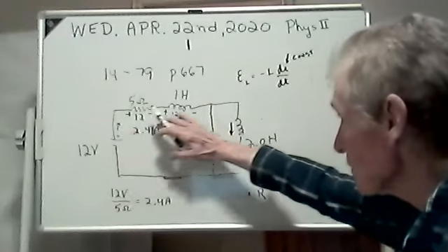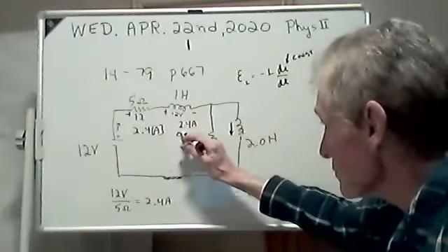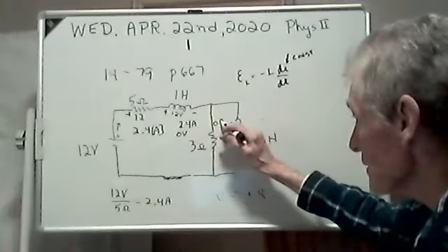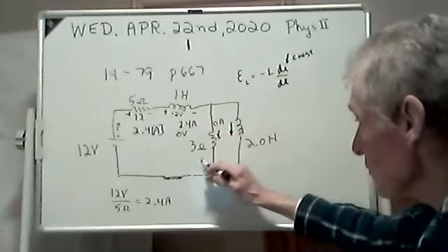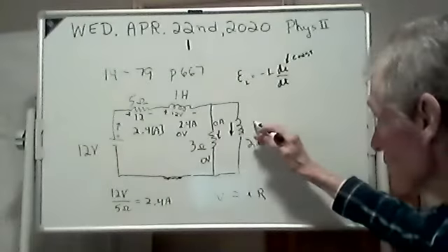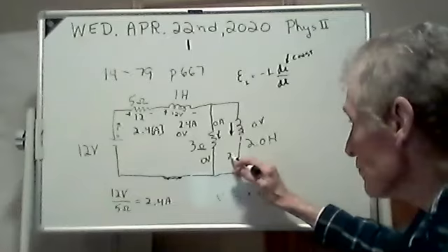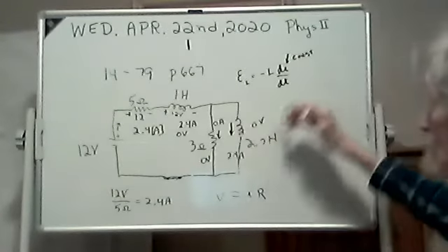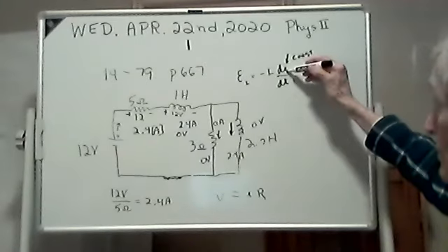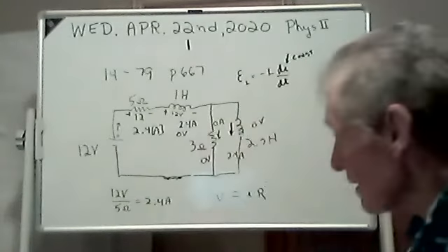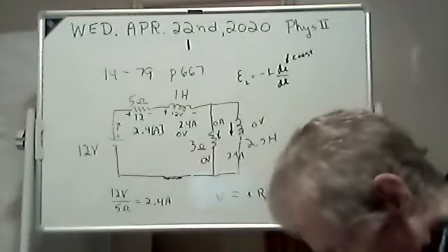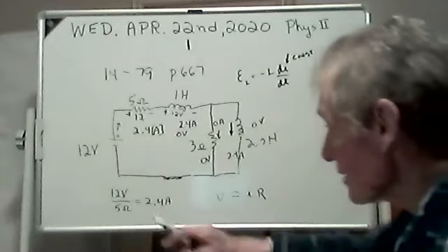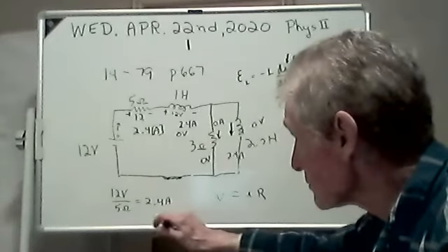The 2.4 amps will come through here, but you'll have 0 volts on the inductor. And then you'll have 0 amps coming through here and 0 volts. There's no voltage, so there's no current. 0 volts, but you'll have 2.4 amps steady coming through here. No voltage because the derivative of a constant is 0. So that's what you have after, how did they put it? Steady state current through the battery. The steady state current through the battery should be 2.4 amps.